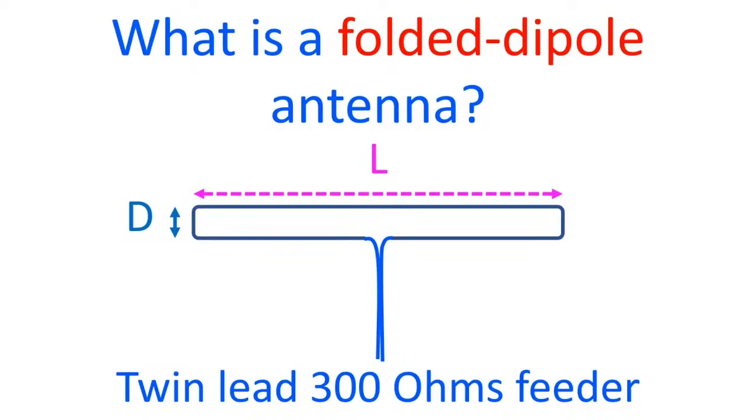Like a half-wave dipole antenna, the folded dipole is also resonant and radiates well at odd integer multiples of half wavelengths. As mentioned in case of half-wave dipole antenna, it acts as a 3/2 wavelength dipole at 3 times the fundamental frequency. Folded half-wave dipole antenna is preferred when the impedance has to be higher.